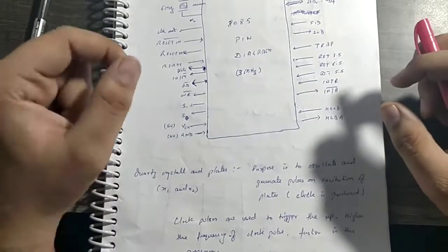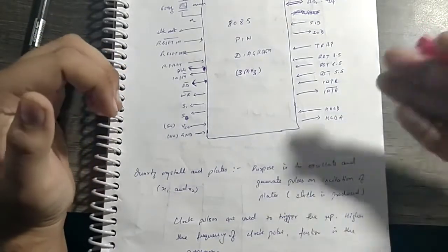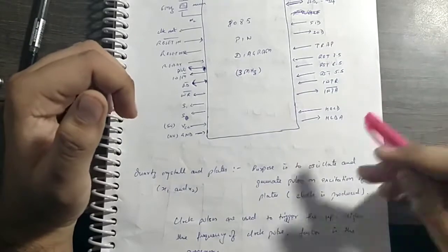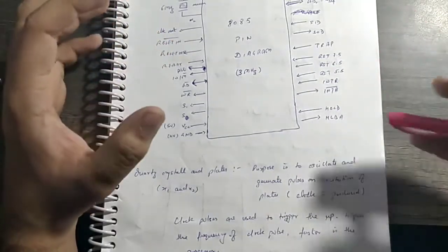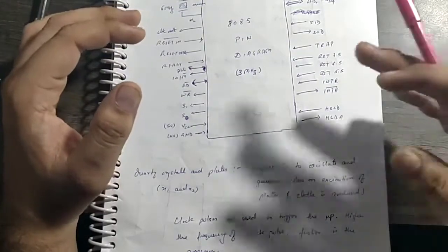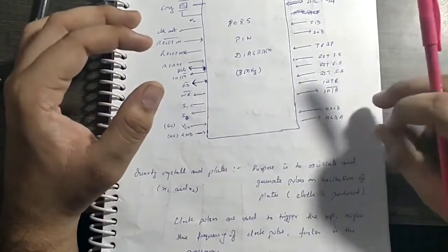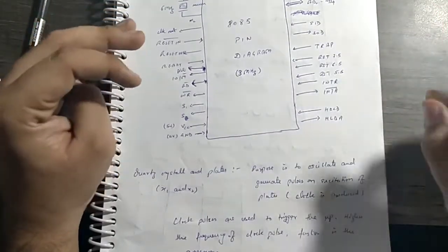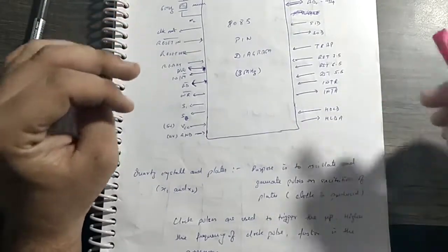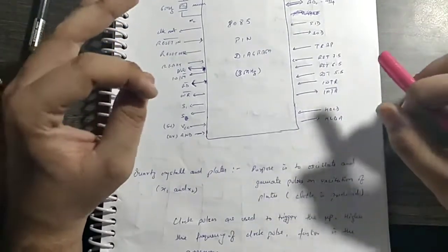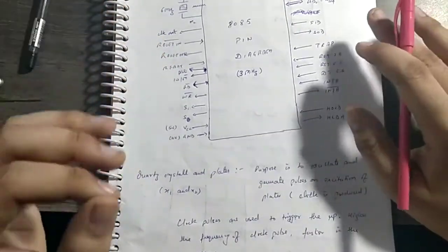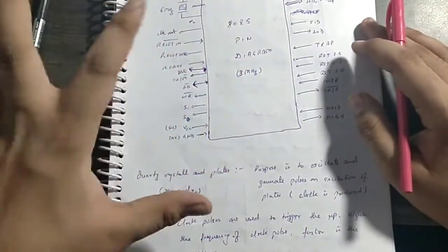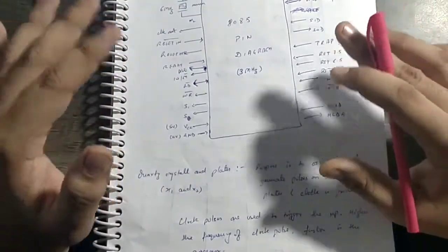After releasing the system bus, the microprocessor acknowledges the hold signal using HLDA. I know you might not get the complete insight. This is a basic idea of what HOLD and HLDA pins are used for. A simple thing, they are used for direct memory access, DMA. DMA transfer is terminated by releasing the hold signal. That's it. We'll be understanding DMA in complete detail in another video.